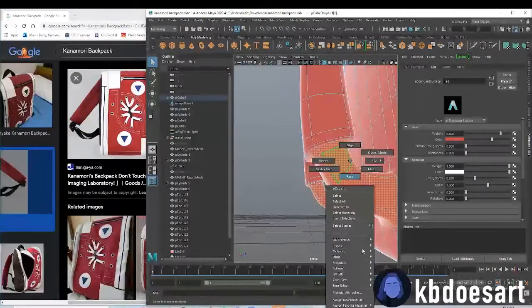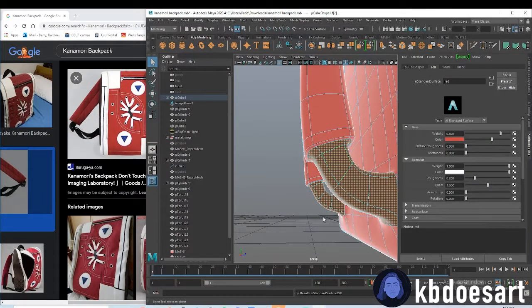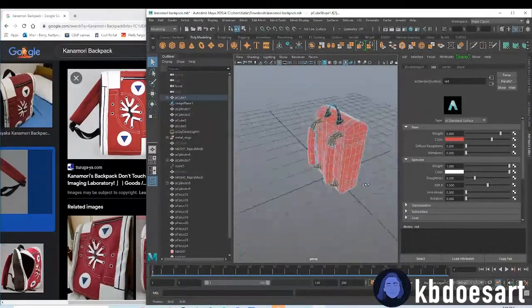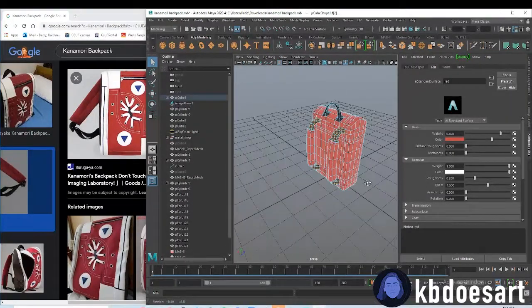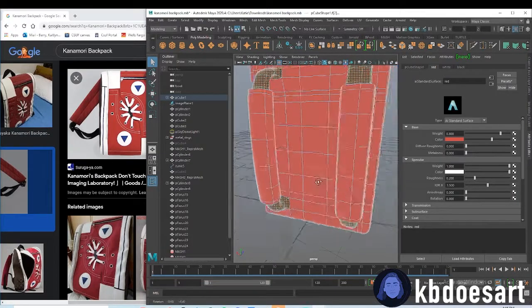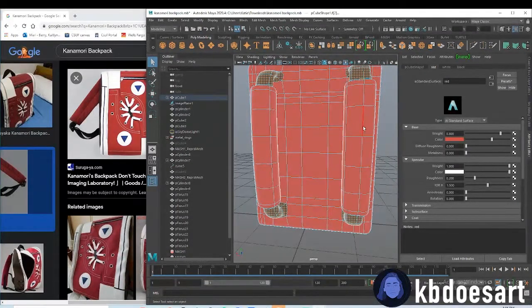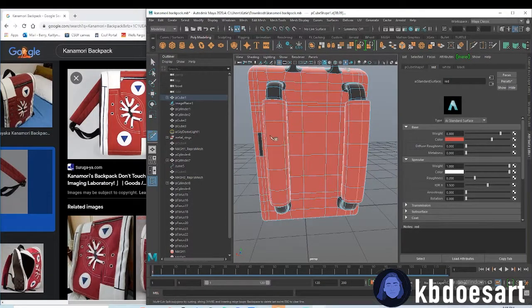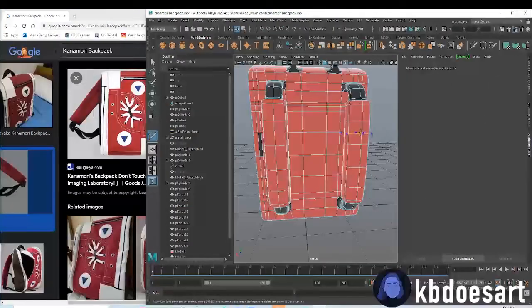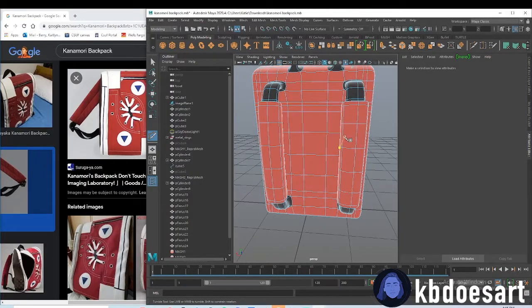Okay, and then just assign that black texture to it. All right, looking good, kind of exciting. I also noticed that I want to take this edge. Actually, let's just add a multi-cut. So grab your multi-cut tool and let's make a multi-cut going relatively down that center.